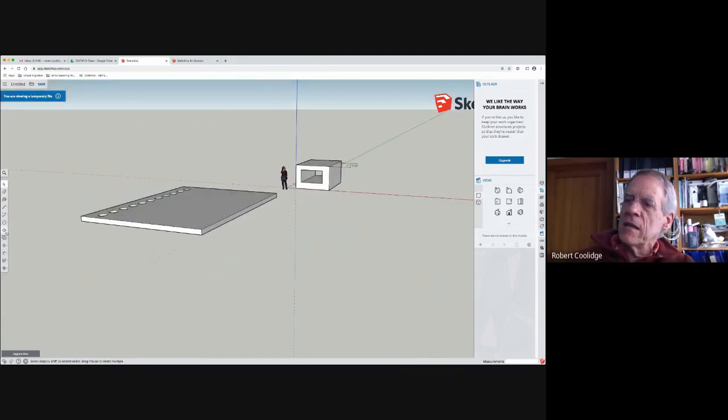You can pick the tool first, the move tool, and it starts hunting for what to move. So right as you hover over stuff, you'll see it light up, like this line. Right now, it's lit up the line. If I click there and start dragging, I move it. So that's verb-noun. You go move and then say this. More often than not, I use it the other way, noun-verb. It's like, take the selection tool and say, pick this. So if something's already selected, then pick the move tool and then move it.